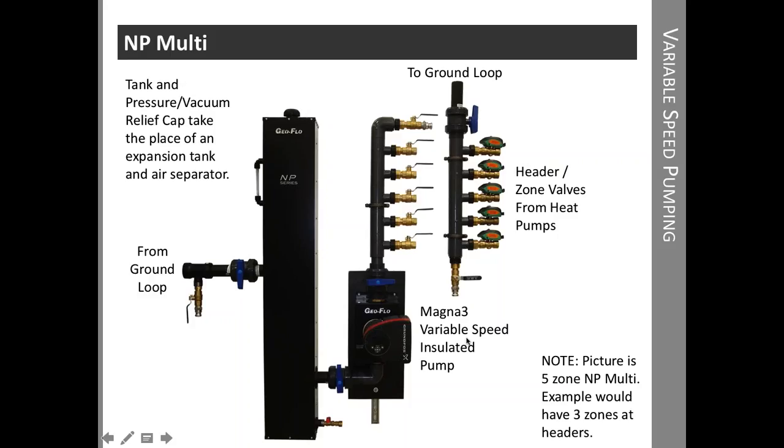Go back and check heat pump flow rates. If we still have more flow than we need, we reduce the head a little bit more. The more you can reduce this, the lower the energy costs are, but also the quieter the pump. It's very, very quiet because it's a wet rotor circulator, just like the small little flow center pumps. But still, if it's running at 100%, it's going to be noisier than if it's running at even 90%. It's amazing how quiet this thing is, just slightly below max.